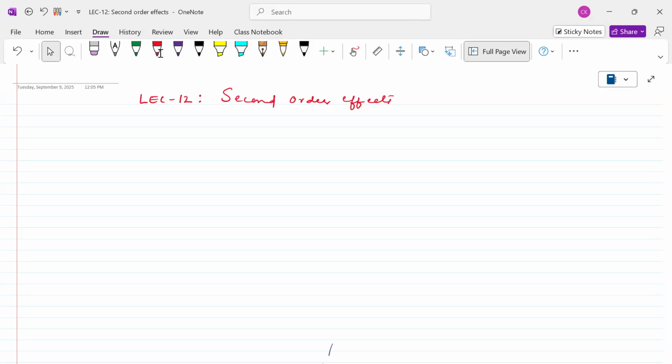Whatever we have seen so far about the current equations in saturation, we maintained the body and source at the same potential. And we thought that when VGS is less than the threshold voltage, the current is equal to zero. But these things may not be true in some cases. In what cases these are not true, we will see now.